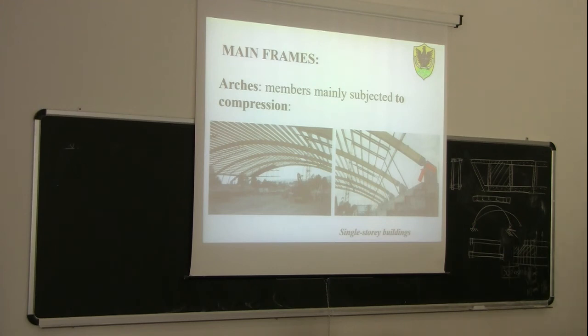So 30 gigapascal. For timber, it is basically 1/3, as some of you were saying. So it's basically 10 gigapascal. Since the cross section is the same, if the Young's modulus is 1/3, the deflection will be 3 times.